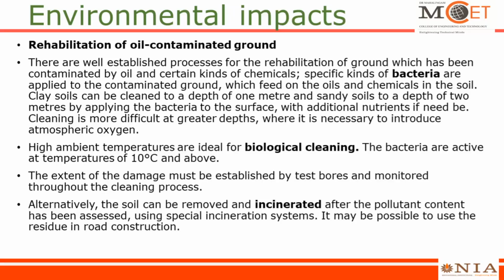Specifically, kinds of bacteria are applied to the contaminated ground which feed on the oil and the chemicals in the soil. Clay soils can be cleaned to the depth of 1 meter and sandy soil to the depth of 2 meters by applying the bacteria to the surface with additional nutrients if needed. Cleaning is more difficult at greater depths where it is necessary to introduce atmospheric oxygen. High ambient temperatures are ideal for biological cleaning. The bacteria are active at temperatures of 10 degrees and above.